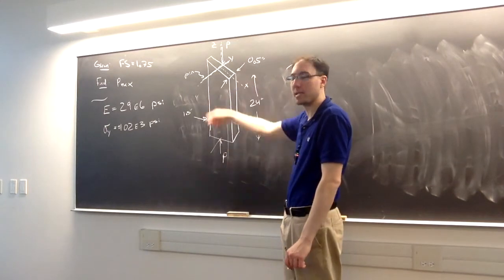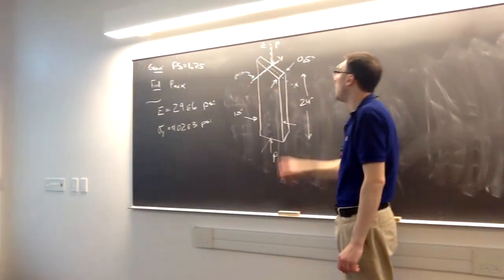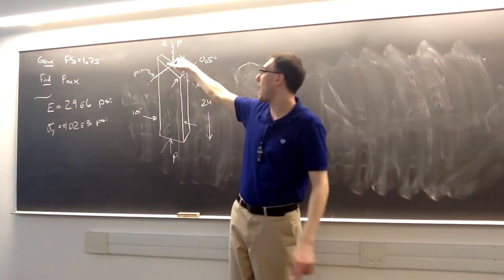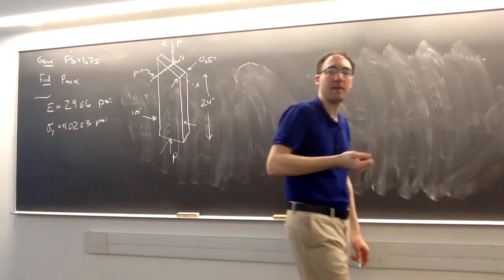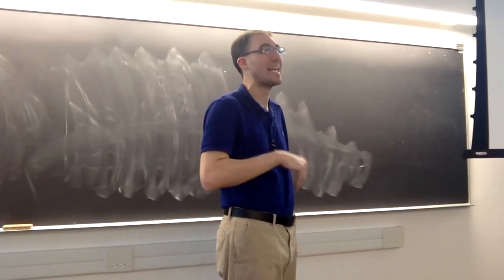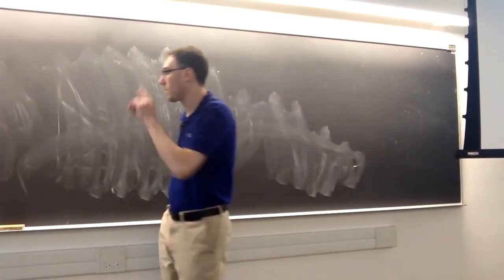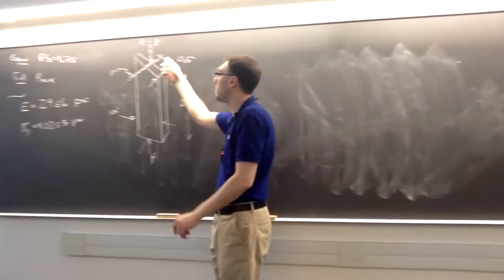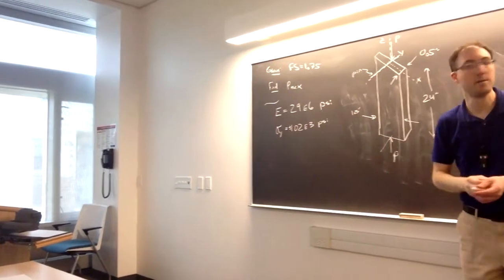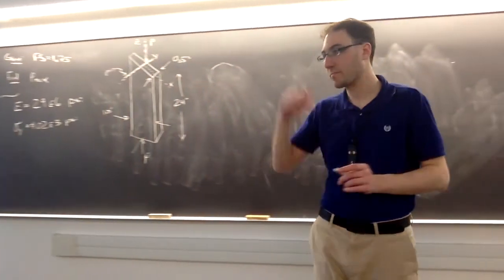That's what makes it a pin at the top, a pin at the bottom. But around the x-axis, that pin is preventing rotation around the x-axis there. So that gives us a different type of connection when we're looking at the buckling around the x-axis. So the pin is parallel to the y, so it's parallel to the shorter dimension in this case.